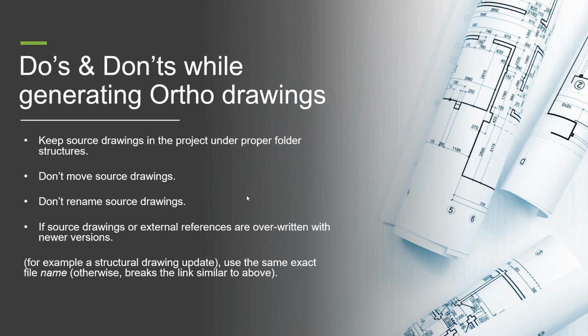If you don't know this, the ortho view is really set up of a bunch of blocks in model space that are 2D representations of the 3D model in that view. And those blocks are linked through the database, the Plant 3D database, to the 3D model components that they represent. So we can regenerate that geometry in the ortho when you update your 3D model through that connection that we have in the project database in Plant 3D.